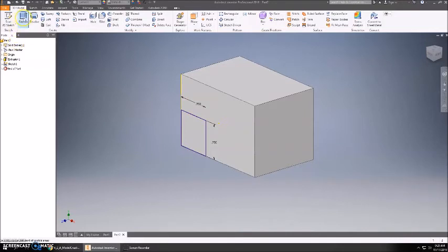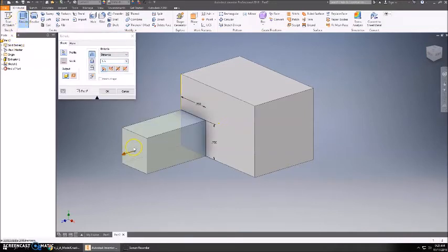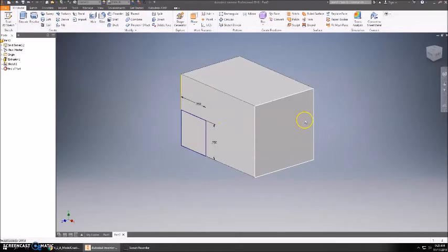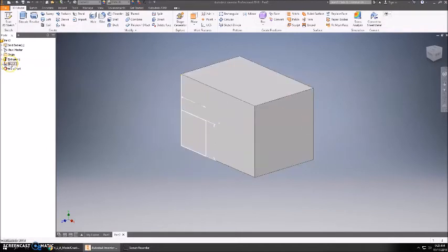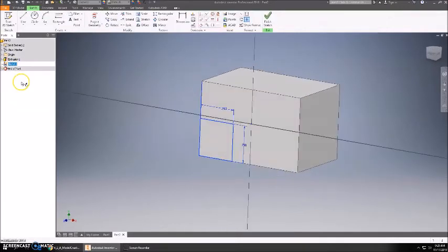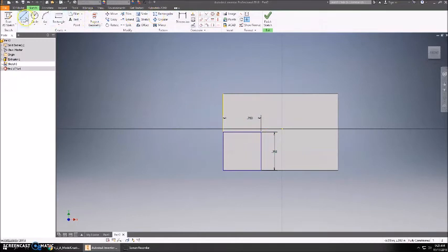And the next thing I'm going to do is go to my extrude, and I actually don't want that area. I actually want the area behind it, and you can see it did not auto-select it. That's because we don't have lines that connect through that. So I'm going to go back and edit my sketch. I'm going to right-click, edit sketch, grab my line tool, and starting at this corner, I am going to come across just like this and add those lines.